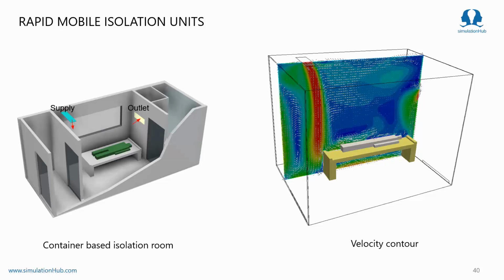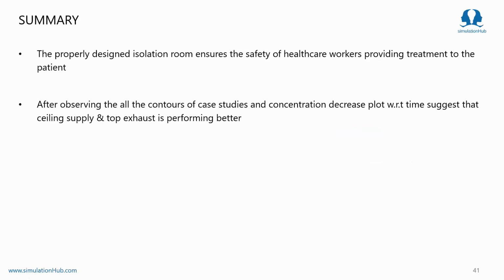One important thing to show here is that to maintain 12 ACH, you may get heavy, high velocity on the mannequin, and due to this there is high draft, and a thermal comfort problem may arise. So this is a typical example. Here also you can use the same CFD setup and analyze everything in detail. So not going into detail, moving ahead, let's summarize our case study 1.